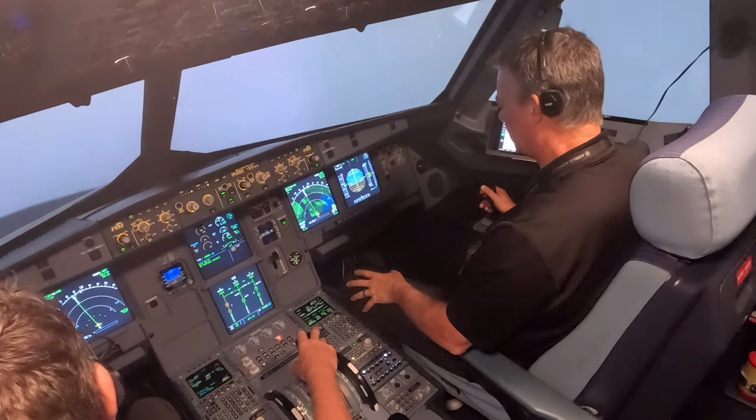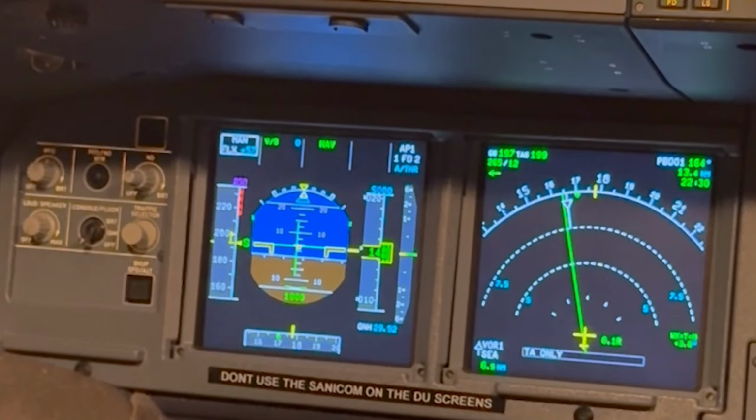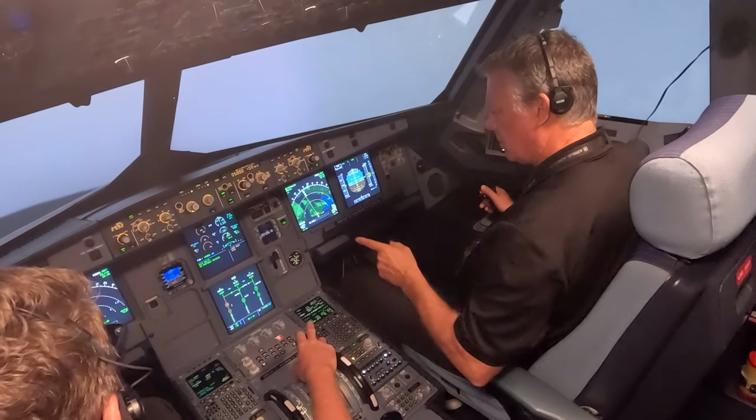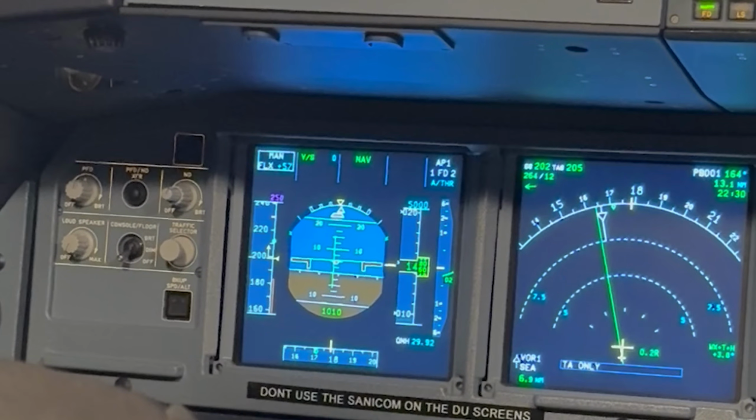Remember to stop ECAM prior to any configuration changes. Flap 0. Speed checked. Flap 0. Continue ECAM. If performing a flaps 2 or 3 takeoff, pilot flying may order pilot monitoring to continue ECAM while the aircraft accelerates, workload permitting.